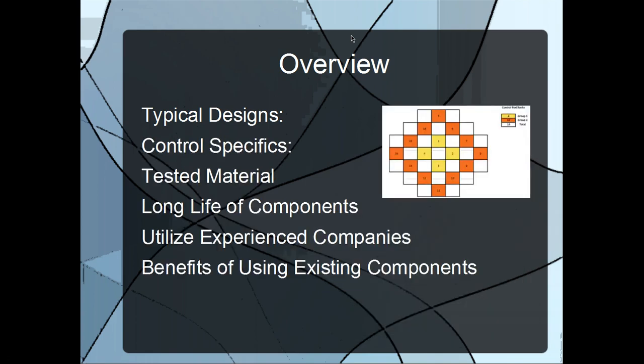The control rod drive mechanisms, or CRDMs, used in the NuScale power module are provided by EMD of Curtiss-Wright. EMD has been manufacturing and designing CRDMs for over 45 years and currently has 5,000 CRDMs operating in 88 plants worldwide. The models being used in the power module provide precise power control with a qualified life of 7 million step changes.